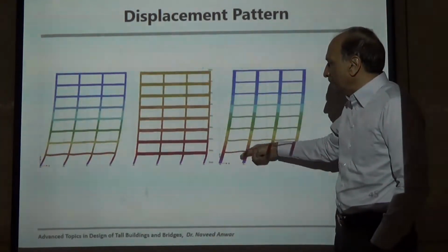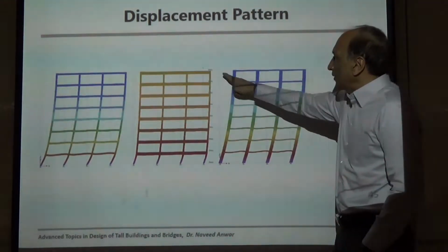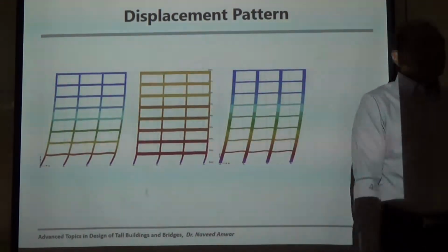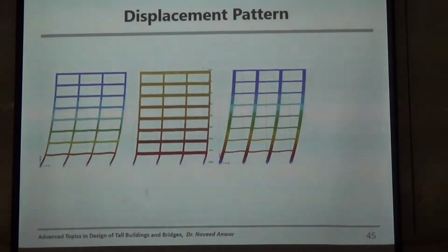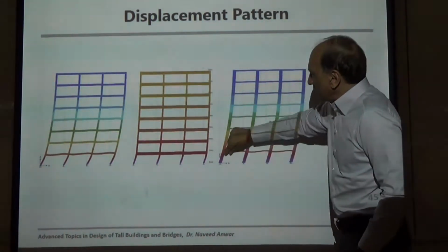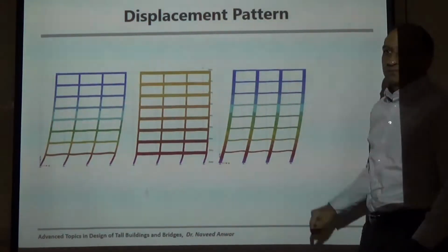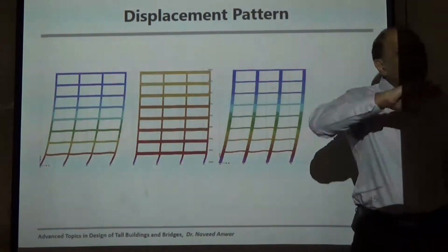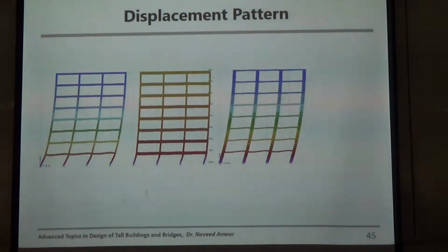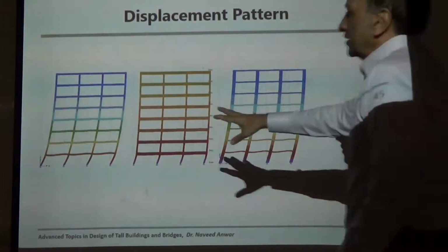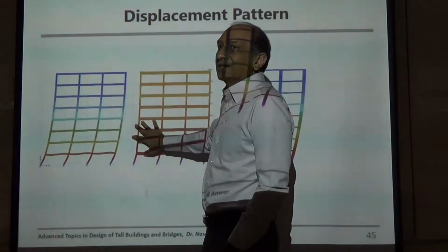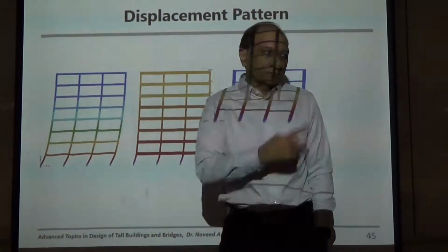And if you're using flat slab, then this is normally the case. But the problem is lateral deflection. Sway is too high in that case, because each column starts to act like a cantilever, kind of, because the beams do not provide much stiffness comparatively. So the sway is very large. That's why for tall buildings, frame alone does not work very well above a certain level, right? For short buildings, this is the case, or this is the case, then it can work. But this is not something that we want.